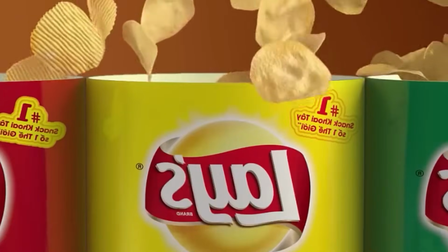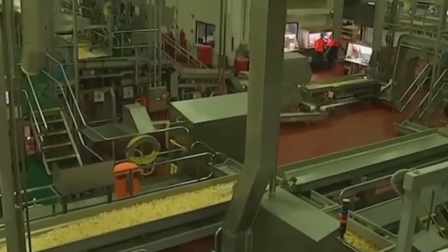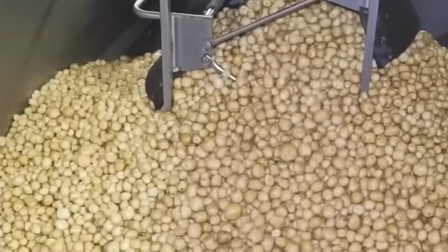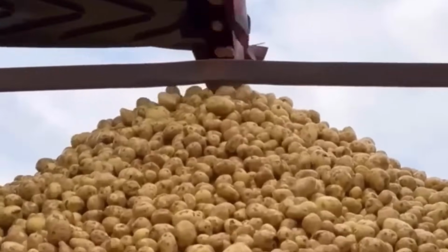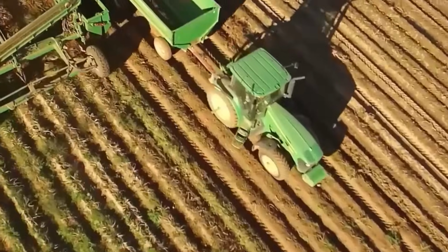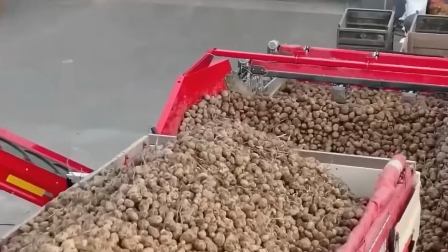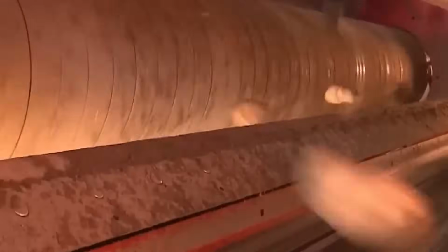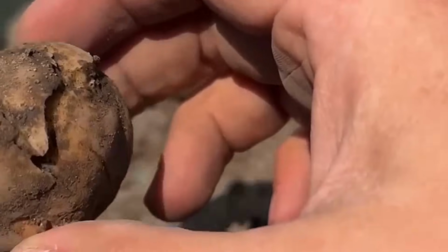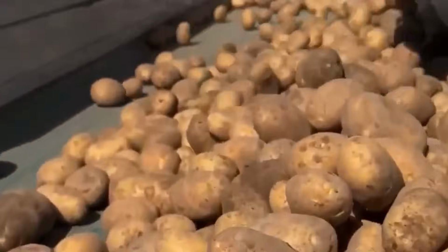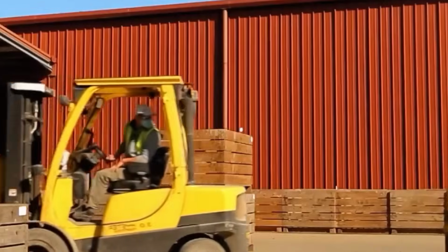Lay's production begins with the intake of bulk potatoes delivered by truck or conveyor into receiving hoppers. Potatoes are unloaded into flume systems filled with recirculating water, which use hydraulic movement to carry them to the first stage of processing. This flume system not only transports the potatoes, but also initiates pre-washing to remove surface soil and debris. Upon exiting the flume, the potatoes enter a rotating drum washer fitted with abrasive surfaces and high-pressure spray nozzles.